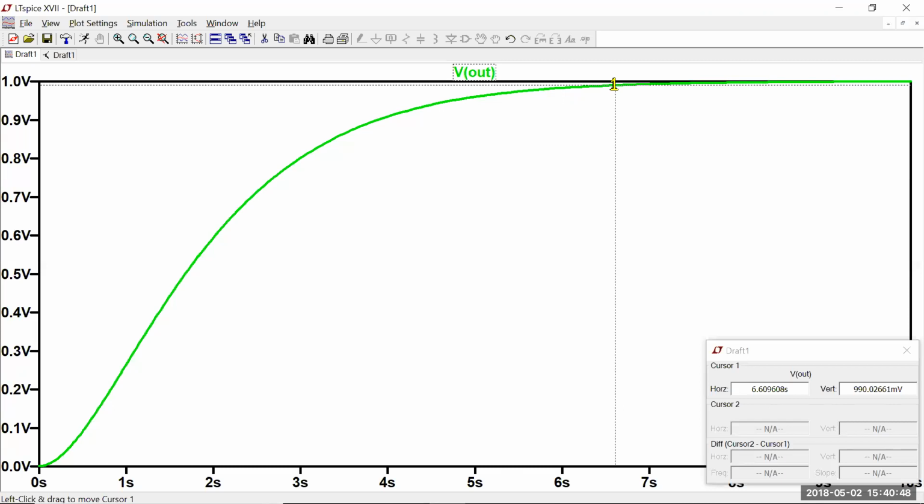It seems like it, but I think on job interviews, you would lose them. And they say, no, tau is for a first order system, and that's with the understanding that 5 tau is somewhat of an arbitrary standard. e to the minus 5 could have been e to the minus 6, because even at e to the minus 5, it's not really settled to where it's going.